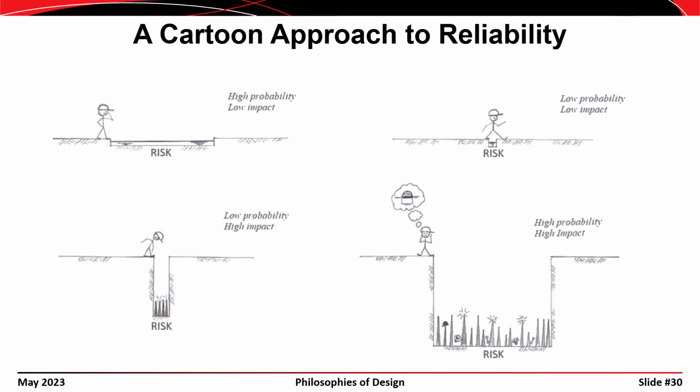For example, the image in the lower right might represent the failure of a component under gravity loads. Gravity loads are applied to the structure frequently, and in general, the consequences of a failure of a beam and column are high, in some cases possibly leading to the collapse of a structure. So for this case, we design loads at their arbitrary point in time level using relatively conservative load factors so that the likelihood of damage under these loads is small. In other words, the building must be immediately functional after the gravity loads are applied.